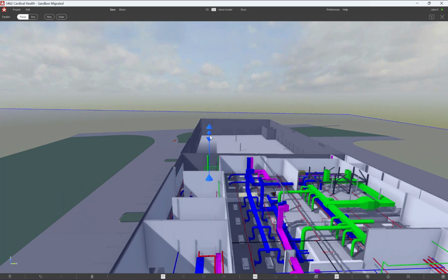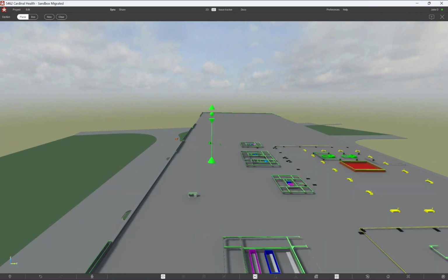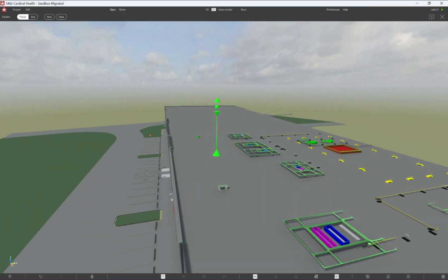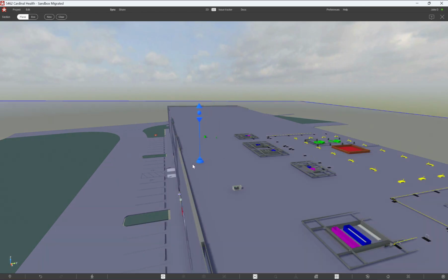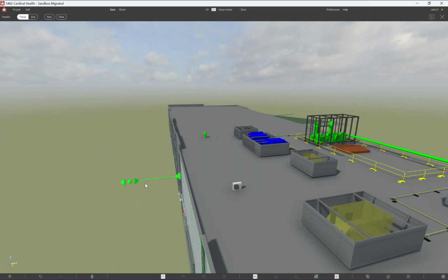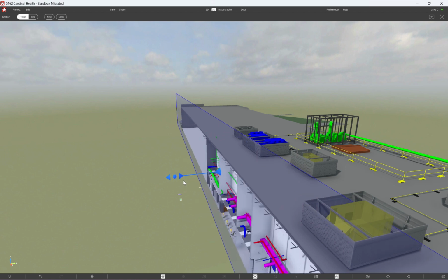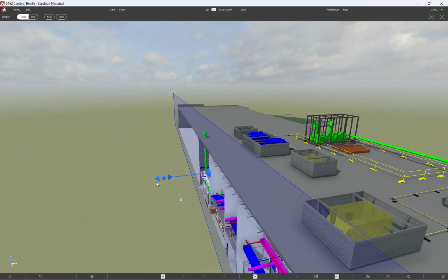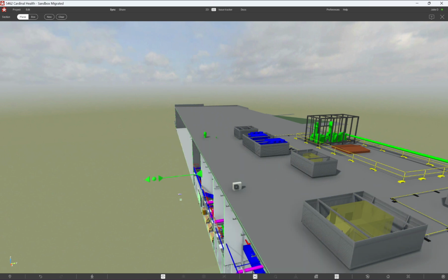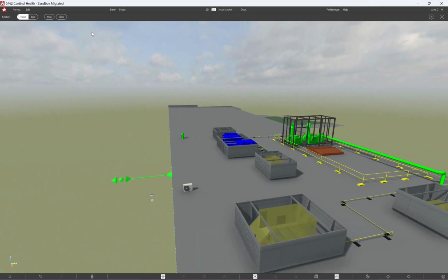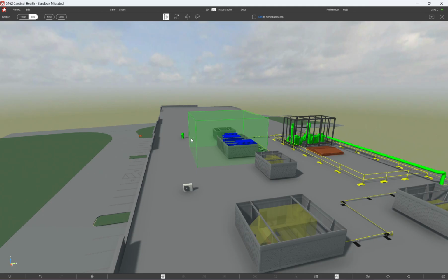Simply drag the icon down to cut down and up for up. And if you want to cut the side of the building here, you can do the same. This bottom will just snap to whatever surface, and you can do the same. Drag to cut and drag to bring it all back. And not only do you have this plane, but, as I showed you before, there's this box. I'll show you some of the other options with this.